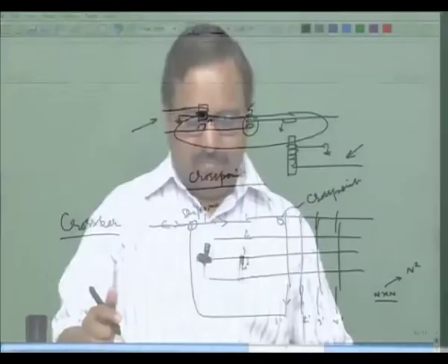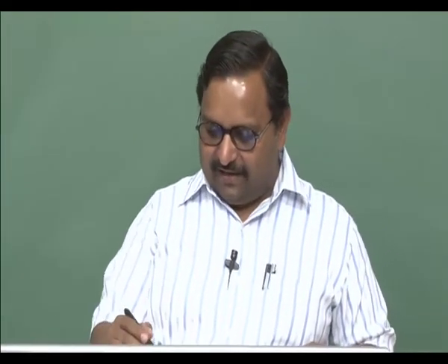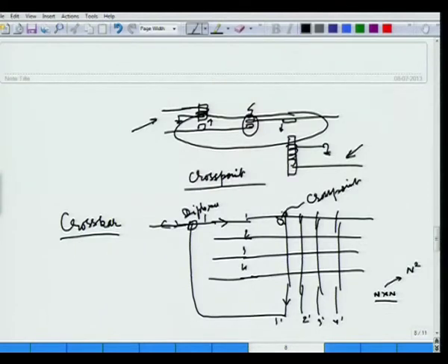This can be reduced by using only the upper triangle or lower triangle, because I can connect 1 to 1 through this, which of course will never happen, but a 1 to 2 connection can be made through this cross point as well as from this cross point. If it is unidirectional, I require both the cross points to be operated, and if it is bidirectional, for example this link, it is nothing but mechanically connecting the wires, so the signal will travel both ways. So, I only need to operate one of these two. It all depends on this.